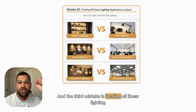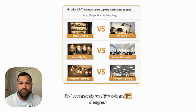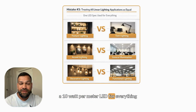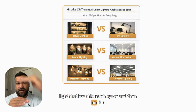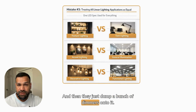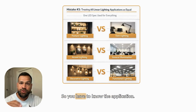And the third mistake is treating all linear lighting applications as equals. I commonly see this where the designer goes on Amazon, they don't know, and they say, okay, a 10 watt per meter LED for everything, or a 4.5 watt per foot LED for everything. They don't understand lumens, they don't understand what the application is. So let's think of a toe kick light that has this much space, and then a cabinet light, and everything's getting specified the same. And then they just dump a bunch of dimmers onto it and think it's all going to dim and work fine. So they treat it as one. So you have to know the application.